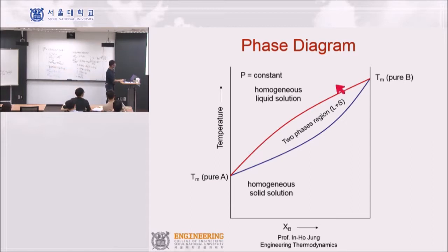And then now, let's look at this one. So this one is liquid phase, yeah, at this temperature. And then in the middle here, let's look at this one. So this is liquid phase. If I cool it down, cool it down, cool it down, now when you meet this one, there's another boundary. And that boundary is connected from here to here, yeah. And then according to this map, everything above this red line is liquid phase. Only single liquid phase. And then if you look at this diagram, everything below the blue line is a single solid solution phase. Single solid phase basically.